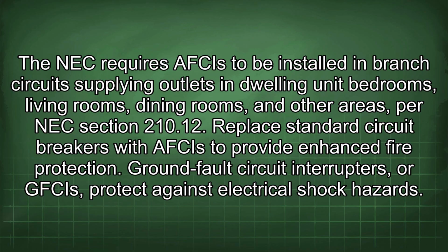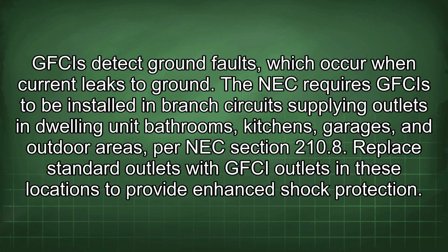Ground fault circuit interrupters, or GFCIs, protect against electrical shock hazards. GFCIs detect ground faults, which occur when current leaks to ground. The NEC requires GFCIs to be installed in branch circuits supplying outlets in dwelling unit bathrooms, kitchens, garages, and outdoor areas, per NEC section 210.8. Replace standard outlets with GFCI outlets in these locations to provide enhanced shock protection.